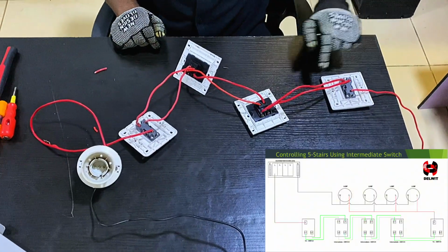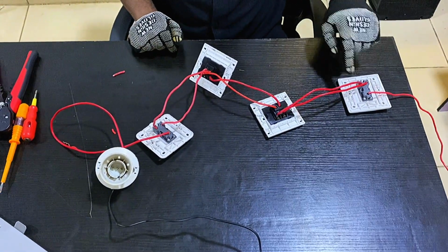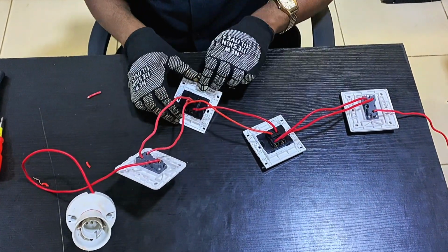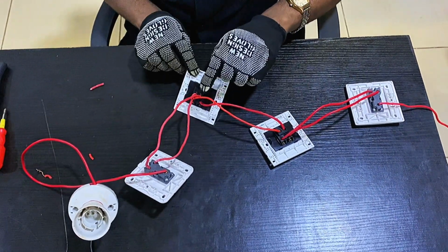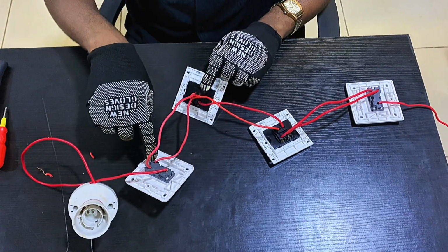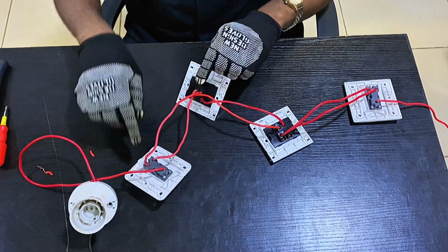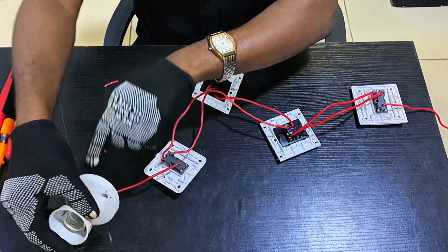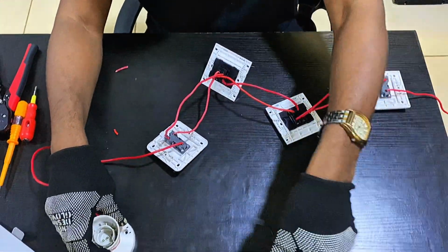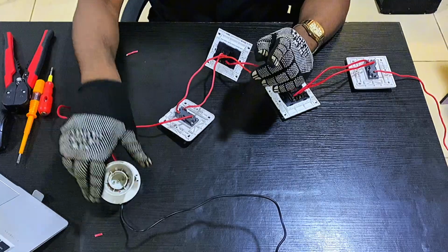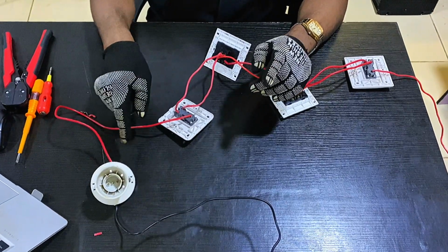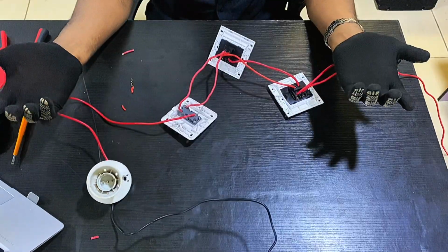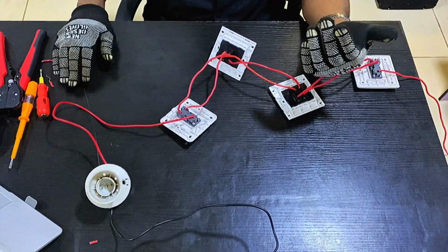So you can see L1 is connected to port 1, L2 is connected to port 2, L3 is connected to port 1, L4 is connected to port 2. The same thing, L3 is connected to L1, L2 is connected to L2. So that is all. Then the common of this last switch is connected to the live of the first switch, then this is the neutral coming from your distribution board. So if there are 4 or 5 lamps, you can connect them in parallel, live to live, neutral to neutral, to as many lamps as possible. So let's test this circuit and see if it will actually work.